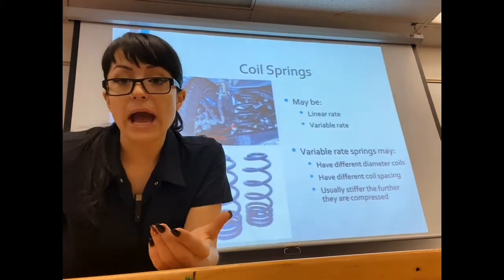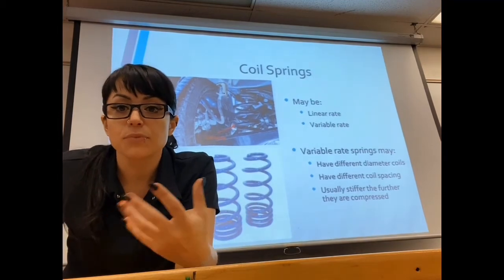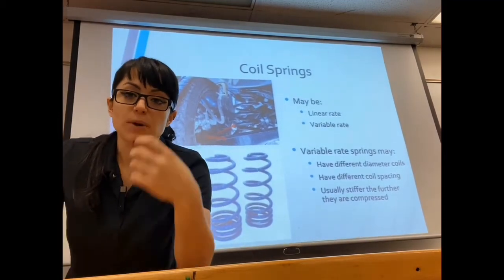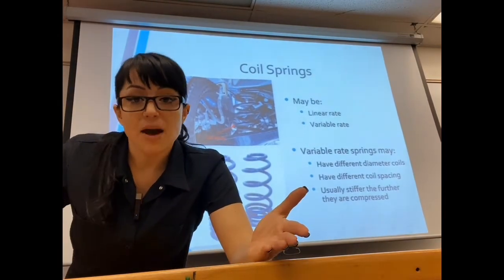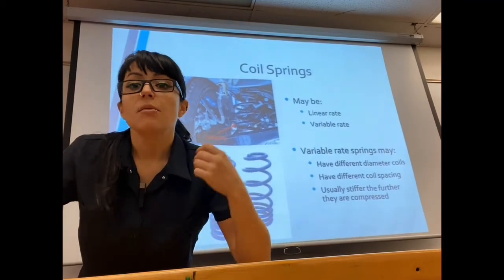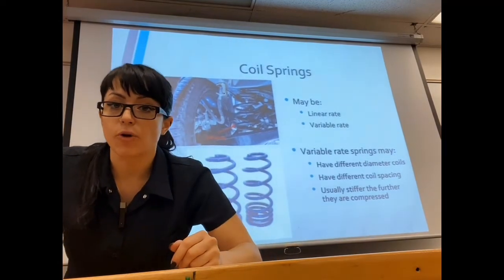So a lot of your aftermarket lowering springs, H&R, Tein, Eibach, a lot of those companies, when they make lowering springs to go on daily drivers, they'll usually make them variable rate. That way you can keep the nice comfortable ride from day-to-day driving, but when you want to ask something of the spring, it will stiffen up a little bit for you.